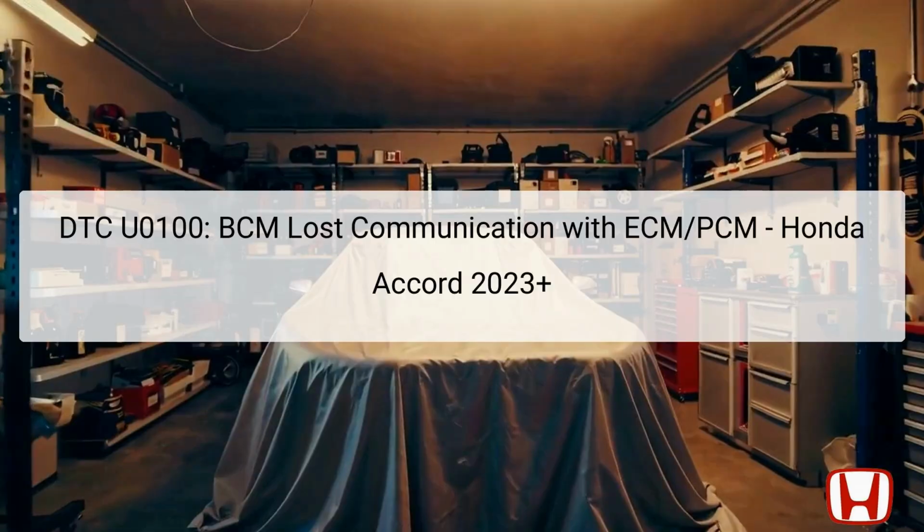The Diagnostic Trouble Code, DTC U0100, indicates a communication failure between the Body Control Module, BCM, and the Engine Control Module, Powertrain Control Module, ECM, PCM, in the Honda Accord 2023 and newer models. The BCM is responsible for managing various body functions and communicating with other modules, while the ECM, PCM oversees the engine and transmission operations. When the BCM fails to receive the specified data from the ECM, PCM, it identifies this abnormality and records the DTC, indicating a communication breakdown.